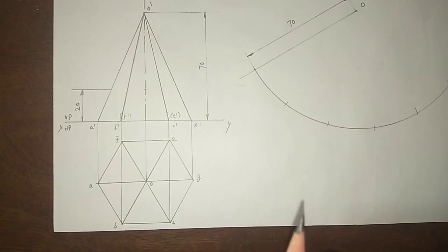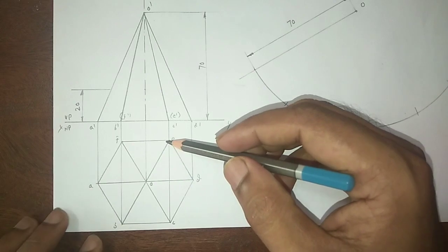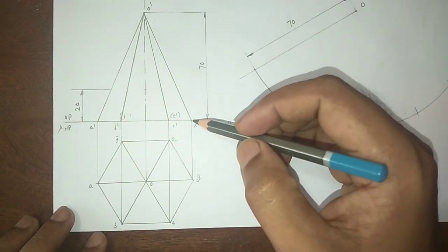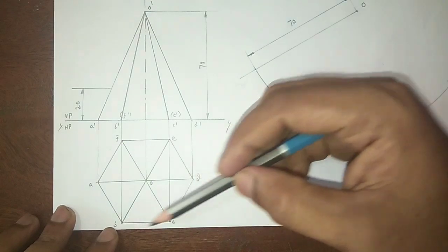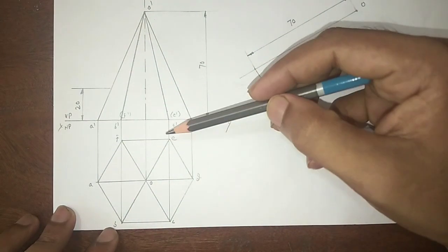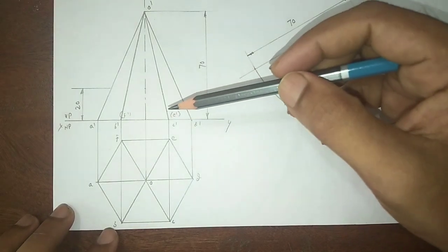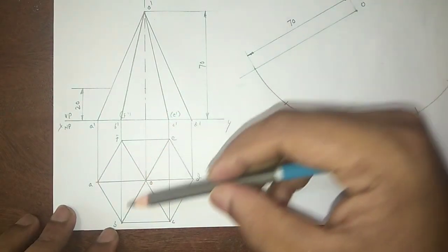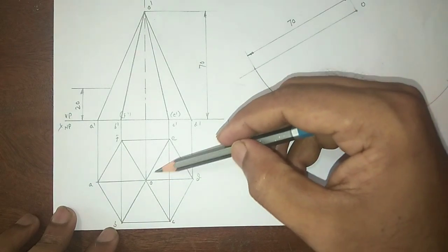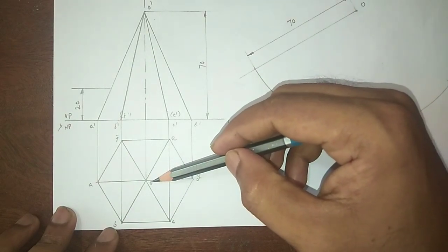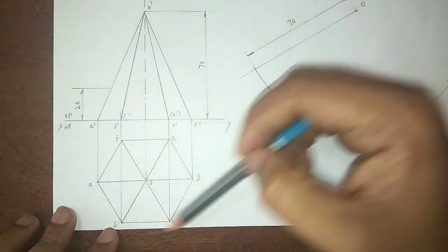When we draw the hexagonal pyramid, in this problem two of its edges will be parallel to the vertical plane. So here the base edges BC and FE are parallel to the vertical plane. It is a pyramid, so it has an apex point, so we connect all the corners. In the center of the hexagonal pyramid, this is the apex point O, and the base edges are A, B, C, D, E, F, which we need to mention.